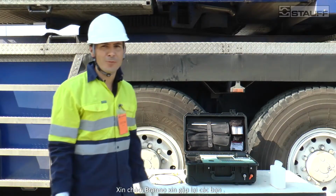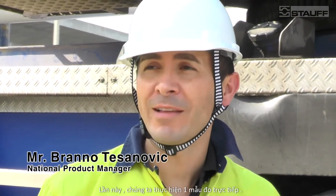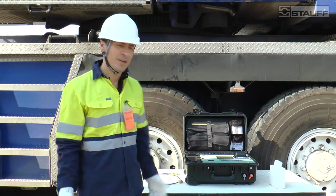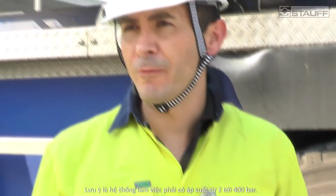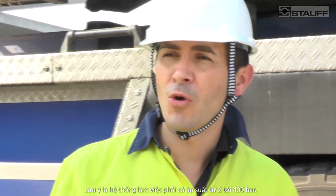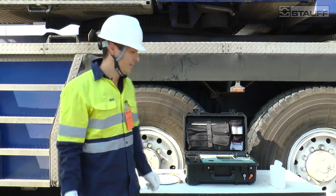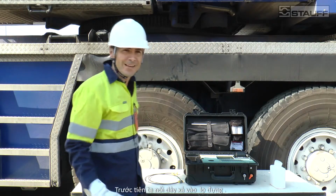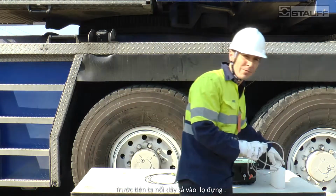Yeah, hi, it's Brenno from Stauff Corporation again. This time we're going to perform an online test. So in this case, the bottle sample is not required. We can connect our particle counter directly to the system. Just ensure before you connect that you have no more than 400 bar of pressure in the system or no less than 2 bar. So the first thing is to connect the waste hose into the waste bottle.